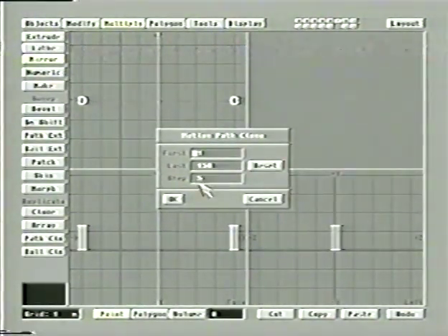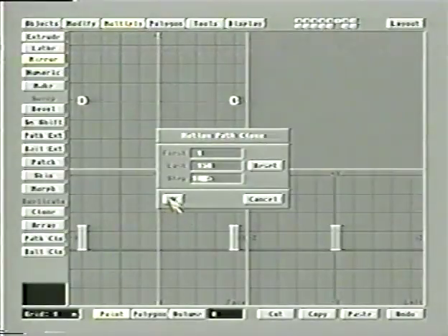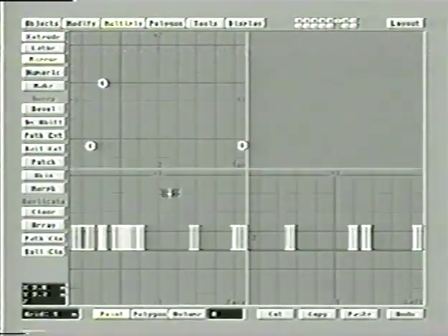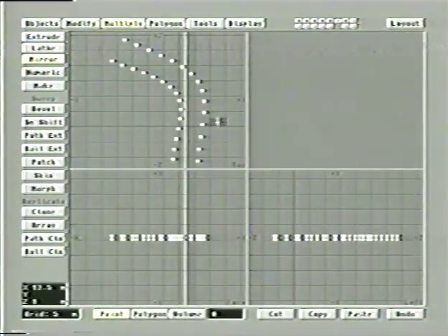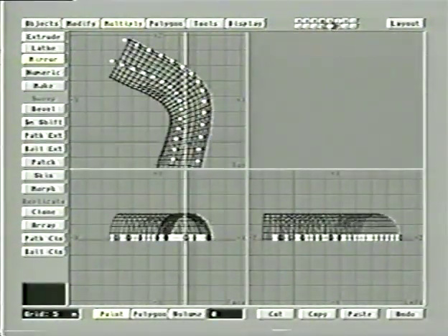If we use this frame step, it's going to put it every 5th frame. So let's actually make it every. Let's give it a step of 10. This way we'll end up with 15 sets of pylons, a total of 30 pylons. 15 sets of these pairs. And there it is. And you'll notice, again, if we look at this in relationship to the tunnel, okay, we're moving along with it. It's fairly close. It's not exactly perfect. It's fairly close.